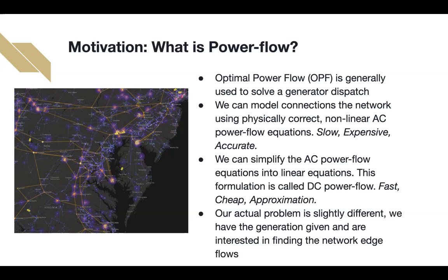We're taking historical data where we know what the generation load actually is, so we're not finding the correct generation. And then we want to be able to recover these voltage angles and voltage magnitudes on the network, so we can reconstruct what the power flow looks like on the network at the lines. So the power flowing between the lines rather than the generation and the load is what we're interested in. And so we'll call this the optimal power flow recovery problem.